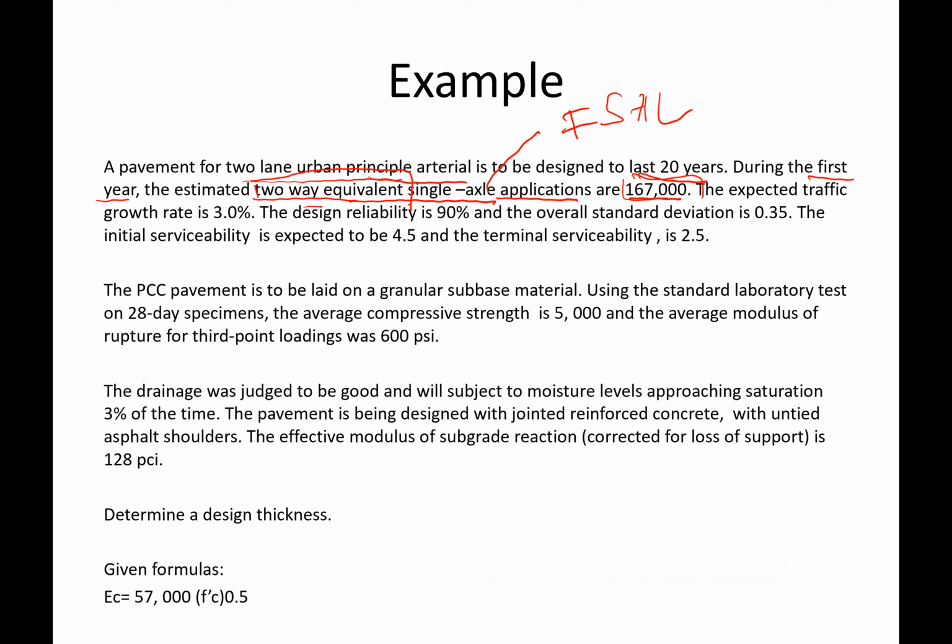It is a 2-lane road. Traffic growth rate 3%, reliability 90%, and the overall standard deviation is 0.35. Initial serviceability was recorded at 4.5, and terminal serviceability is 2.5.